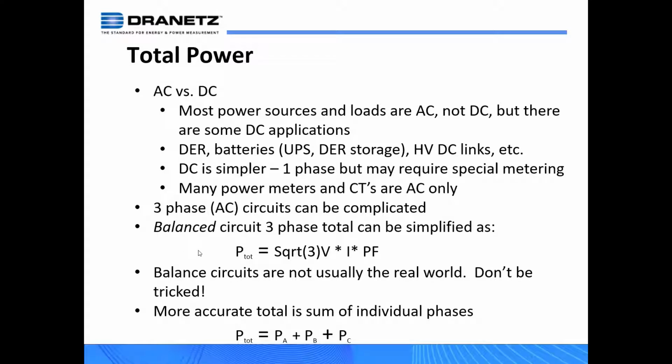Just to get something out of the way, a lot of people are still under the impression that you can just take one phase and multiply it by 3, and that's the total power. Really, that only works in a balanced system, and that's not the real world. Maybe a load such as a motor may consume power in a balanced fashion when it's operating correctly, but that's certainly not the real power feeds.